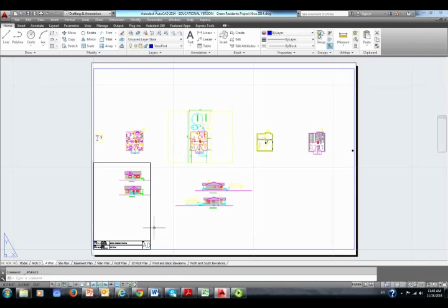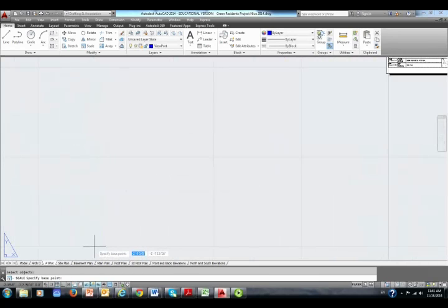In paper space, I'm going to pick a scale command, and I'm going to pick just lines of the title block with window. I am going to also pick this line, just so I am sure that I have this last corner. Scale. Now select objects, enter. Base point, I'm going to, with OSNAP on, make sure you can zoom up closer. Whoops. ZP.